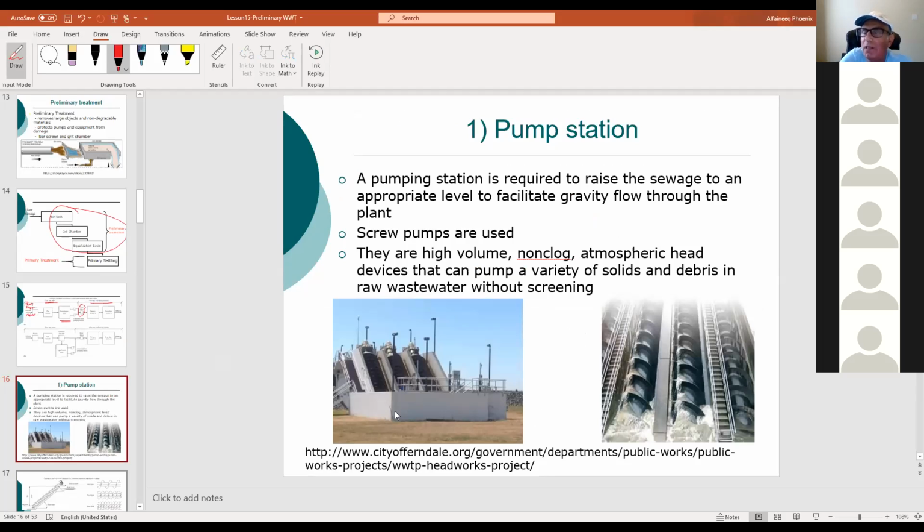Okay, this is a wet well. And you see that the pumps are going down to the bottom of it. And here somewhere, you have the stilling basin beneath after these. The kind of stilling basin, all right? This is where you're gonna start your hydraulic profile. This is from where wastewater is gonna start running through the plant by gravity.